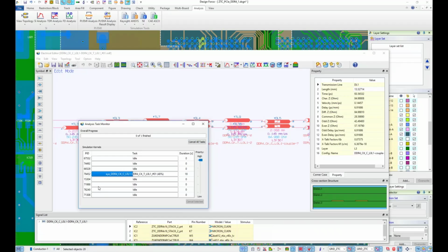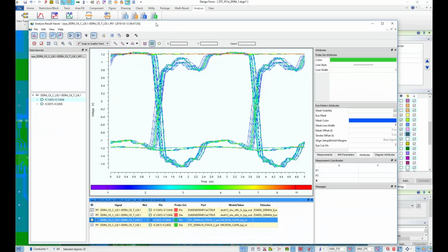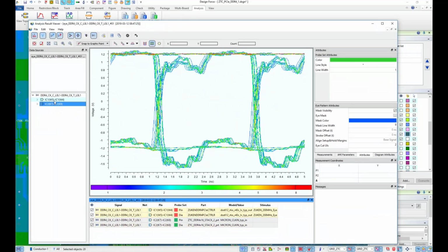As I did mention, it's collecting all the different waveforms, the rising and the falling edge, convoluting them and creating an eye, by that doing all the different variations, including different jitter aspects. And this is then creating the eye diagram result of the selected signal. And this is the result where you can toggle between driver and receiver.